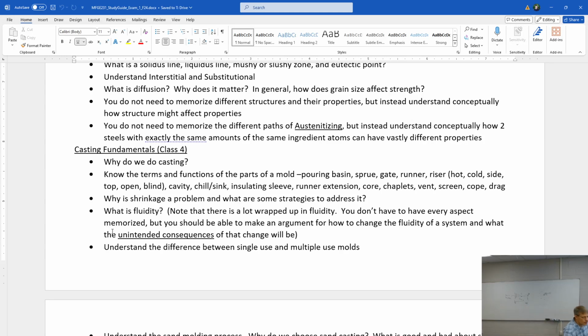Based off hot work or cold work? Not for austenitization. So cold work can definitely do that, but not as far as this is concerned. That is another path to two different sets of properties. Just by changing the crystallinity? Okay, changing the crystal structure, yes.